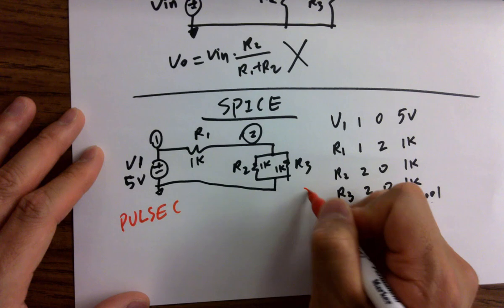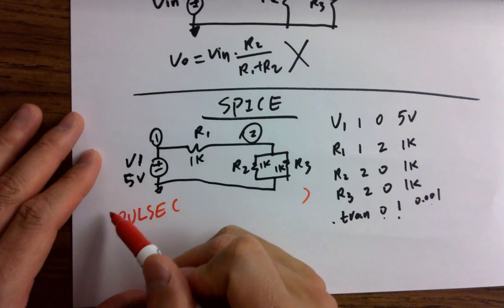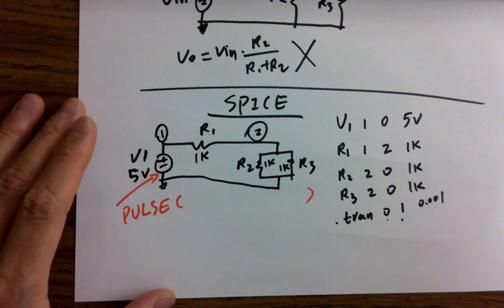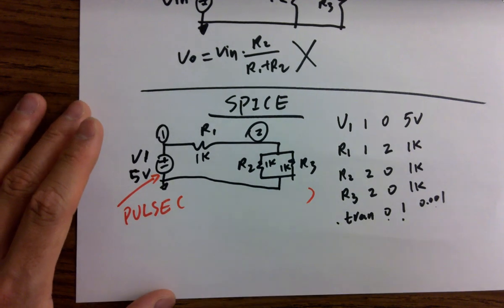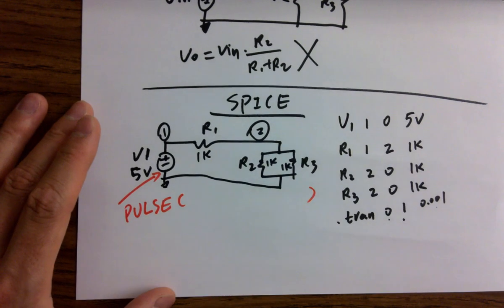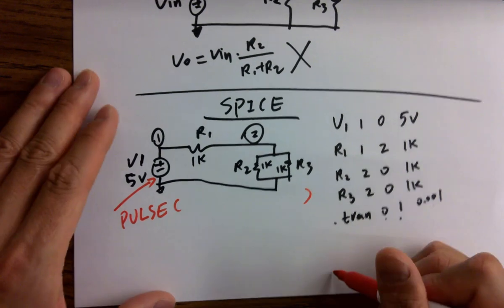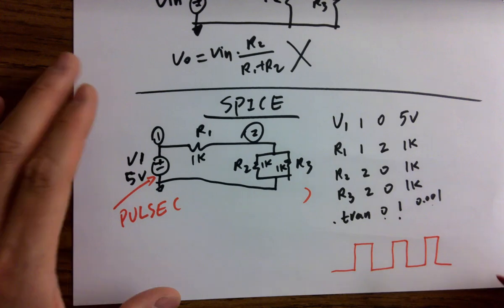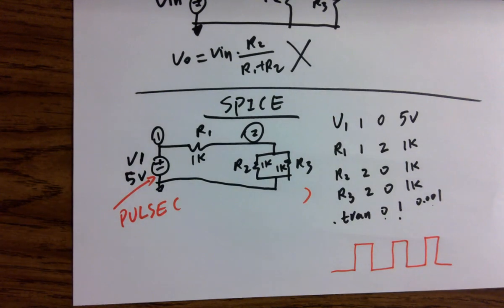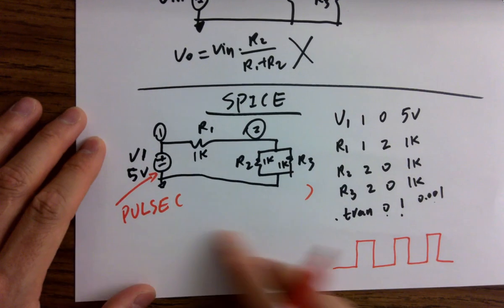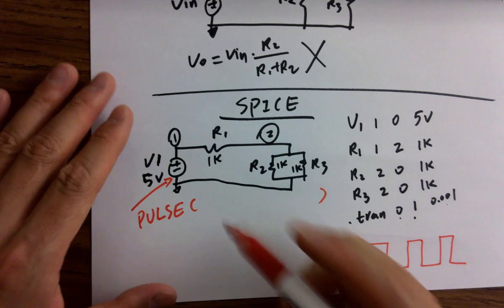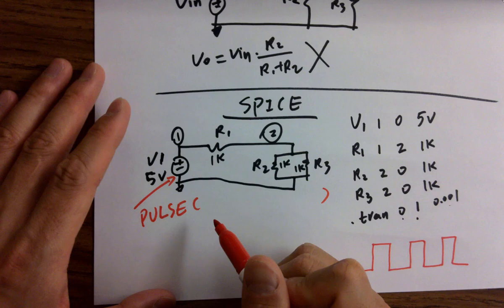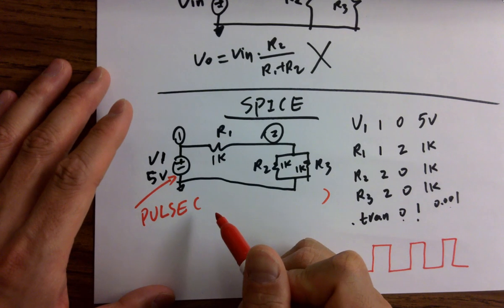Okay, pulse function. So that's a voltage source actually. You grab a voltage source, you right click and change it to pulse. Because it's giving a voltage pulse, a series of pulses. Why do we need that? Because these pulses are basically digital signals, right? Digital 1s and 0s, and that's our stimuli for the circuits. Okay, so we use pulses as stimuli for the circuits. And the arguments inside the pulse are required for you guys. You need to know every single argument inside.